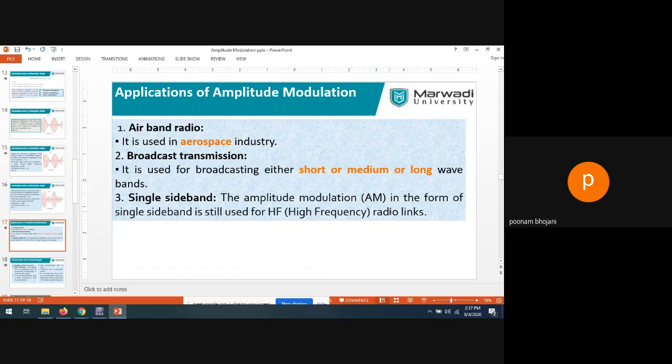Amplitude modulation is also known as DSBFC, double sideband full carrier. But what is the meaning of double sideband full carrier? It means that both sidebands plus the carrier are sent through the transmission medium, so you will require that much power. Now, if you send only sidebands, not the carrier, that technique is known as double sideband suppressed carrier (DSB-SC).